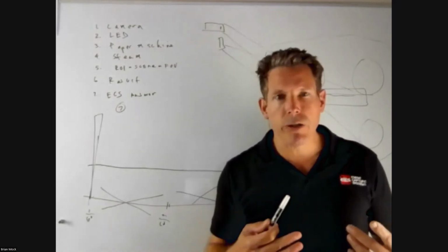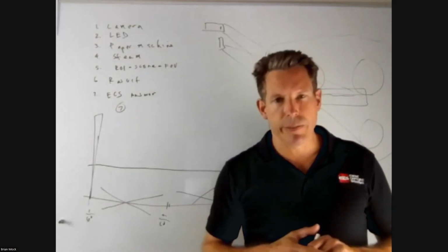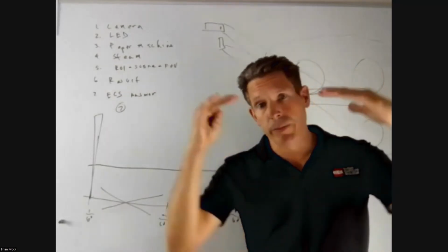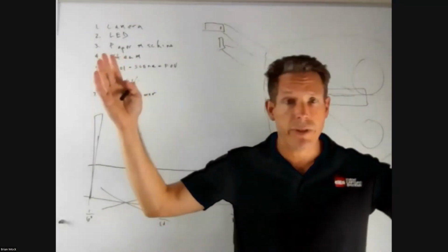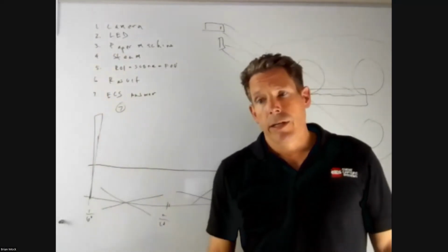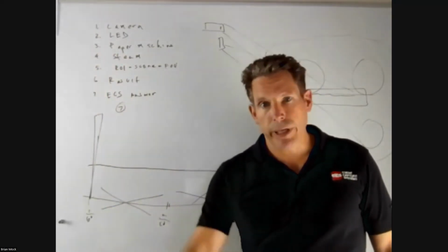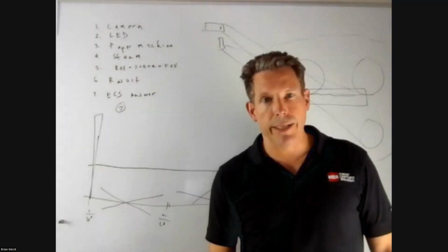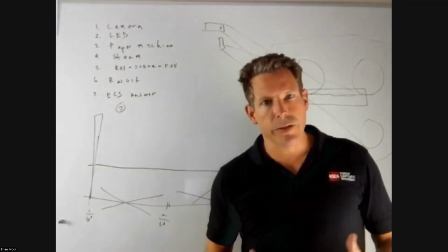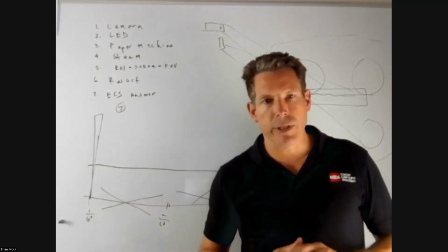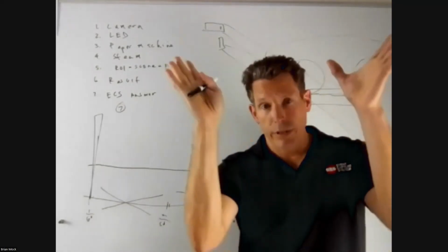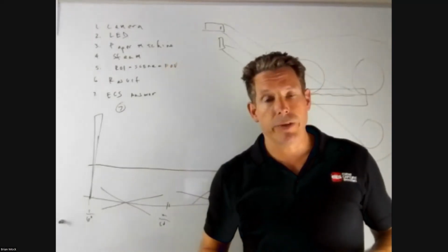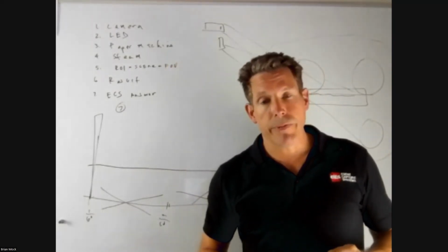There's one example we'll show you later on, in a basement section where you may be up to 30 feet away from what you're trying to look at, and you may be looking at a 280, 300 inch wide sheet. Traditional systems have multiple LEDs down there, a whole bunch of electronics already roasting and dying. With the NIR technology, one light is able to give you enough of that correct energy so that the camera, most importantly, can operate at the correct shutter, correct depth of field,